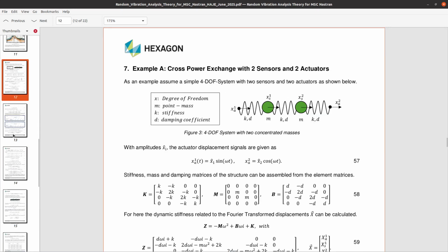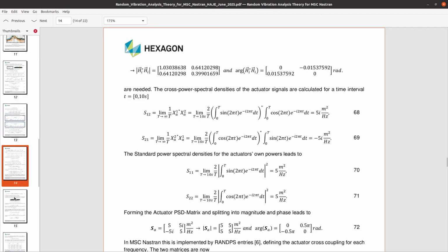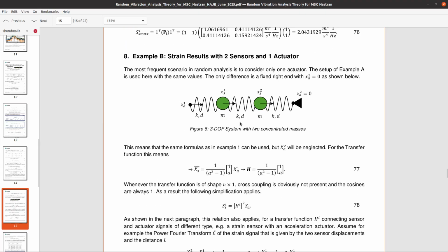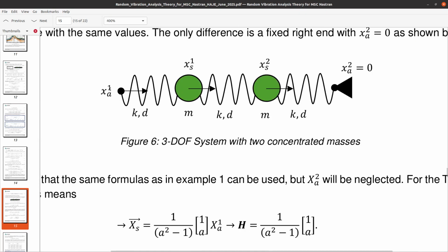So this would be example 8, right? Here, if you look at this diagram, there are 1, 2, 3, 4 nodes. There's a C-bush element representing the spring between all the nodes. Here in green are going to be concentrated masses. The nodes at the left and right, those are going to be fixed, but we're going to have enforced displacements